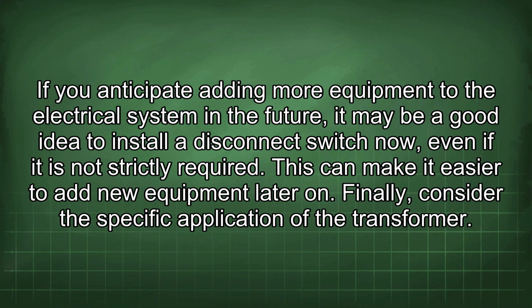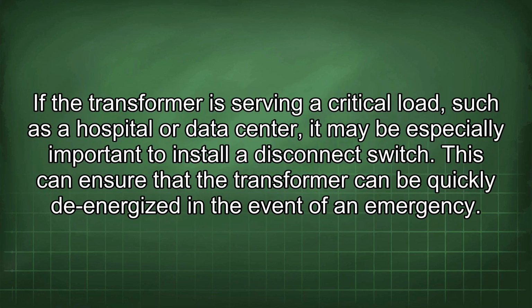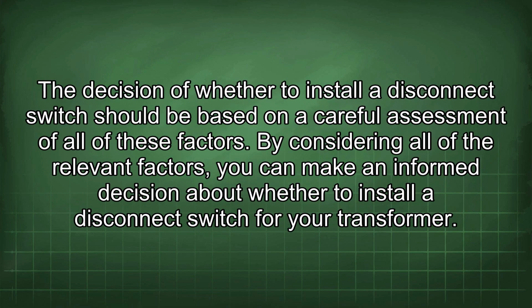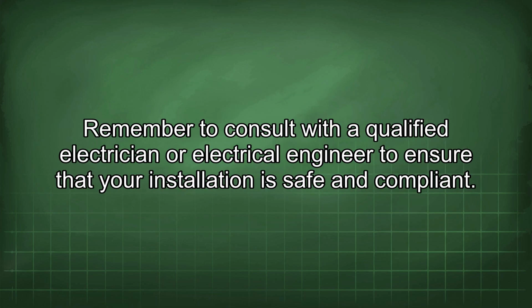Finally, consider the specific application of the transformer. If the transformer is serving a critical load, such as a hospital or data center, it may be especially important to install a disconnect switch. This can ensure that the transformer can be quickly de-energized in the event of an emergency. The decision of whether to install a disconnect switch should be based on a careful assessment of all of these factors. By considering all of the relevant factors, you can make an informed decision about whether to install a disconnect switch for your transformer. Remember to consult with a qualified electrician or electrical engineer to ensure that your installation is safe and compliant.